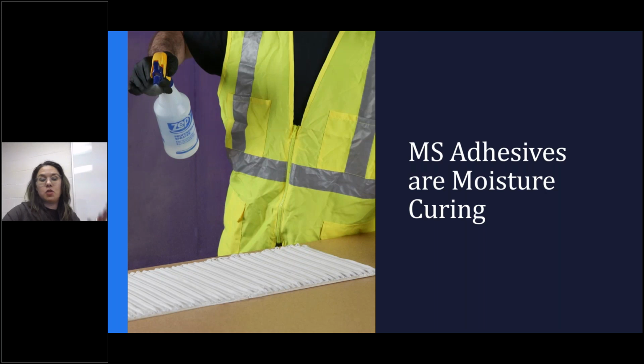With this, if you give your substrate a drink, all you're doing is telling the adhesive to start reacting as soon as it comes in contact with that moisture. So it's a little bit different way to think about it. A good way to remember it is it needs that moisture to react. So you're giving it that moisture and telling it it's time to react now.